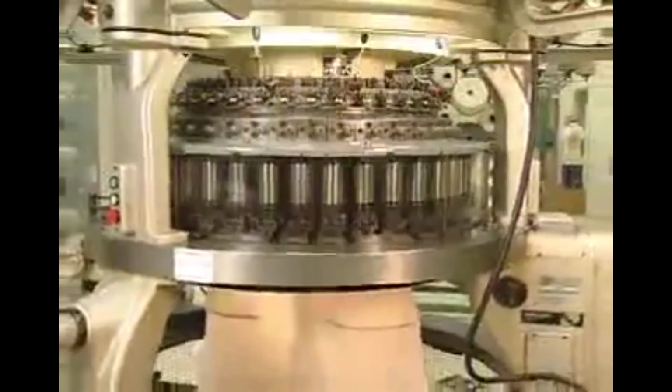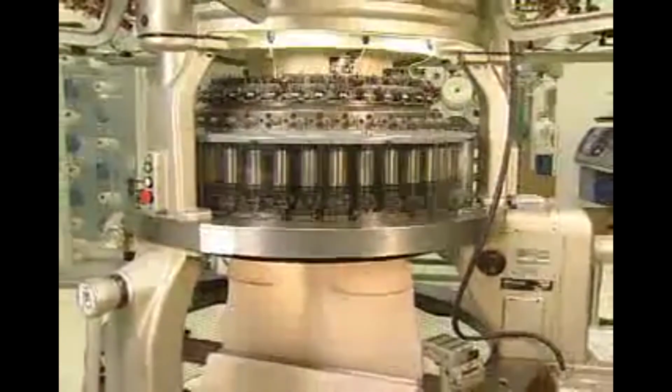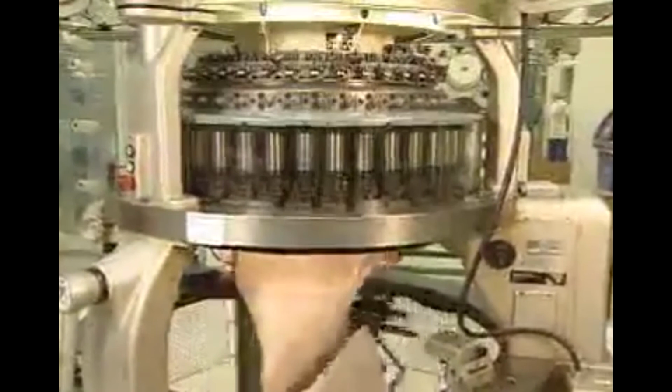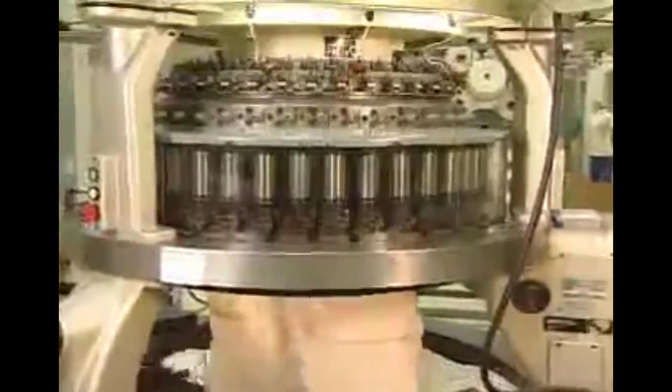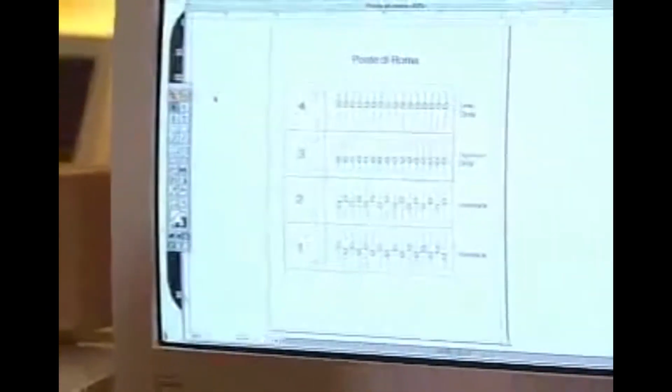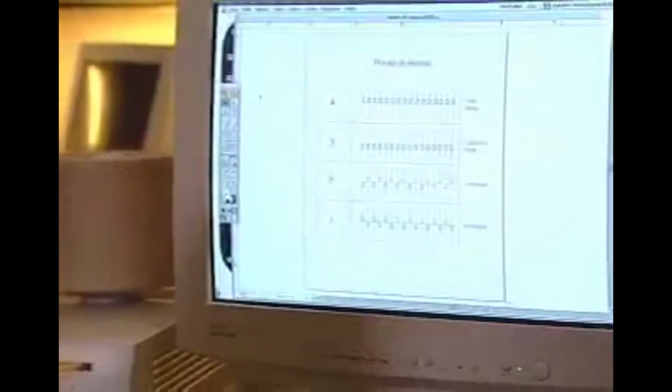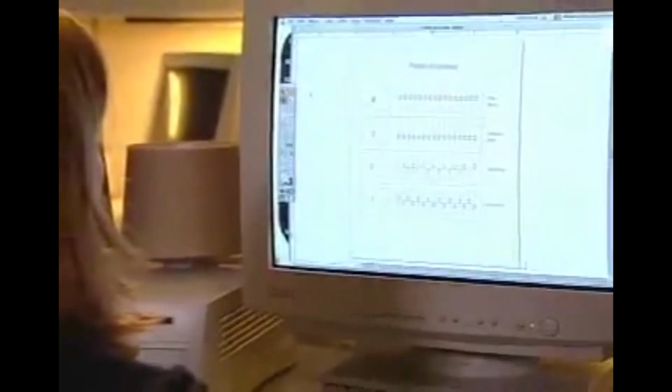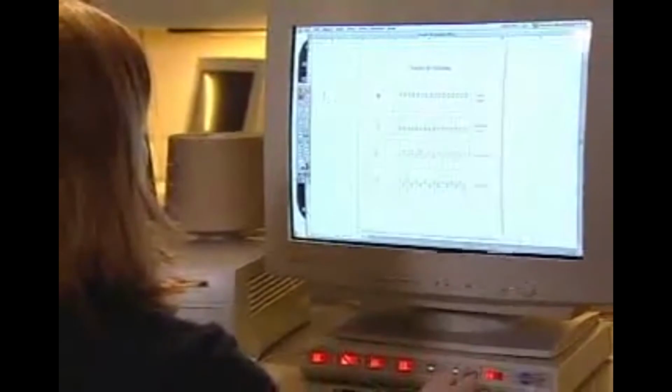Different double knit constructions can be made on rib and interlock gated machines. Needle selection by mechanical and/or electronic systems, along with yarn selection, determines the design effect. A variation of an interlock knit can be used to produce a structure that is tight and stable, where one course of fabric is attached and interlocked while the next is not. Ponte di Roma, used for women's dresses and suits, is an example of this. This fabric has the same appearance on both sides.